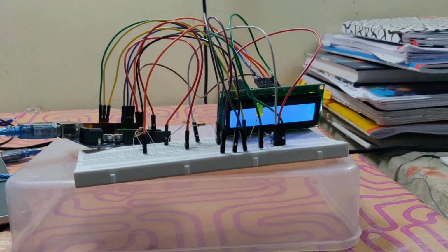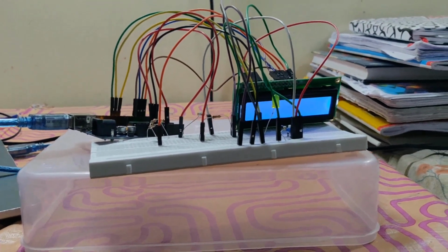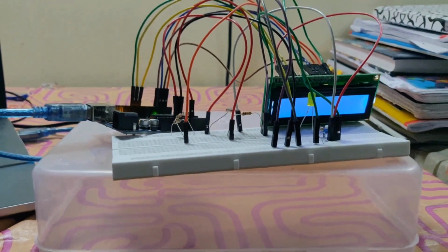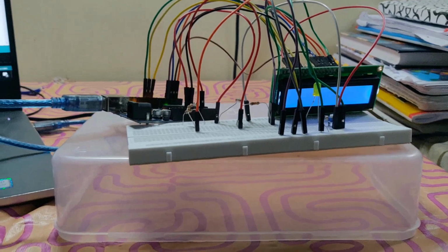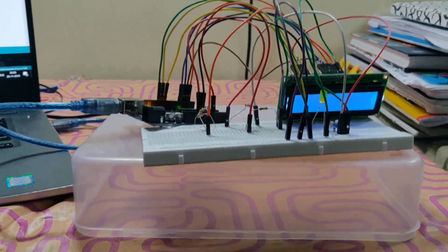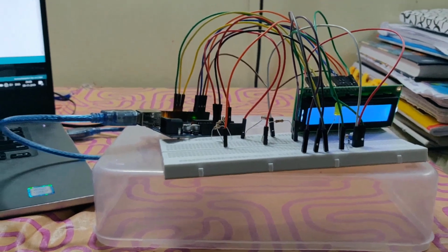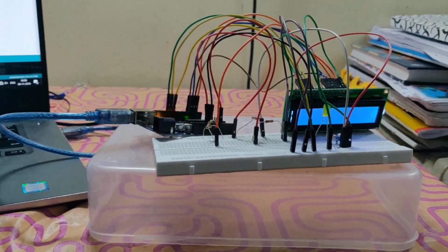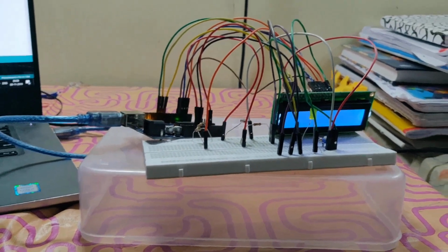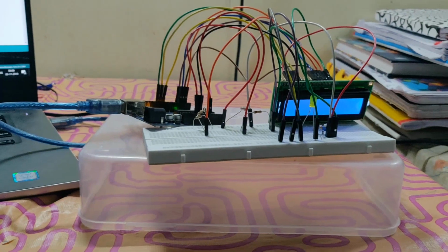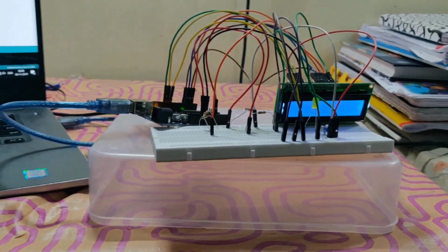Now with the properties of LDR, we are going to give the current to the A0 pin of the Arduino, and according to the logic of our program, Arduino can sense the range of analog values from 0 to 1023. So it will scale down the amplitude of the current into the range of 0 to 1023, and then according to that range we will be setting up a threshold,